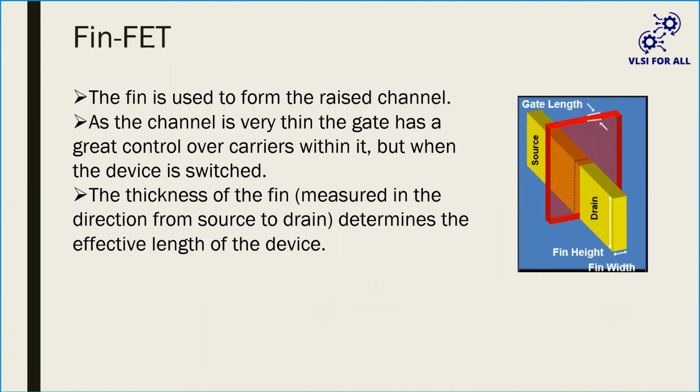Team, remember, we will show you one video to give you a pictorial or visual representation of FinFET. And remember, if you go below 3 nanometer, we are not at all considering FinFET because of issues like mobility. Hence, we go with the gate all around FET.